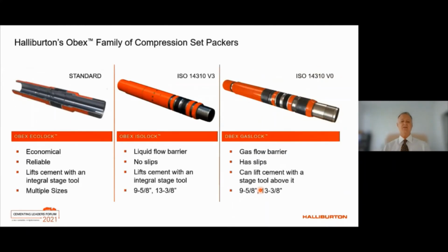Now, I'd like to introduce Halliburton's extended range of OBEX compression set packers that can be run in combination with a multi-stage cementing tool to perform primary cementing of a casing in more than one stage. This will reduce the flow potential factor, reducing the likelihood of sustained casing pressure.